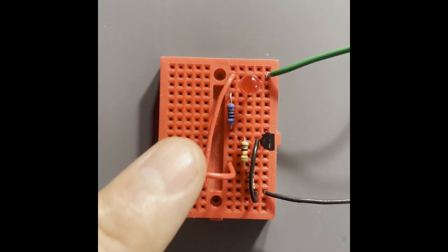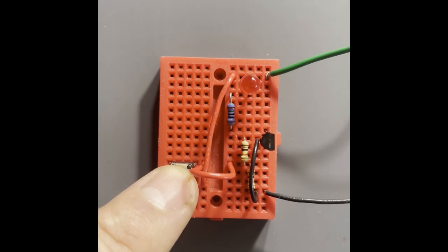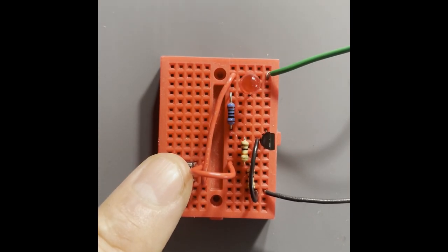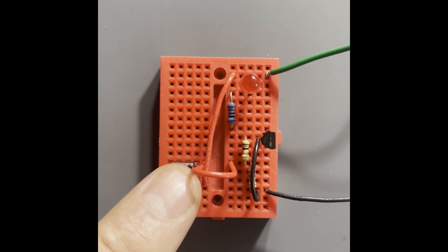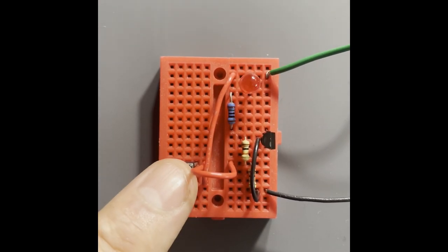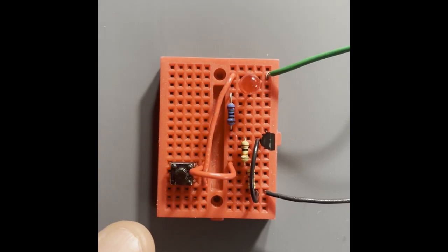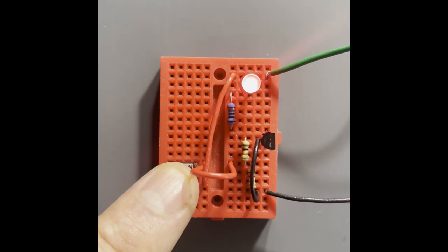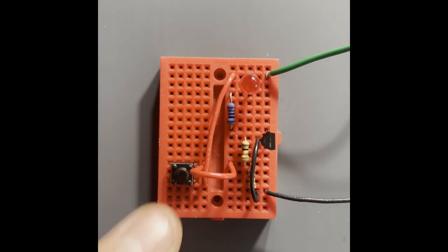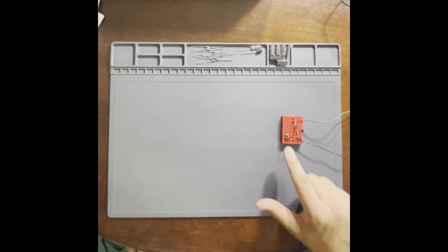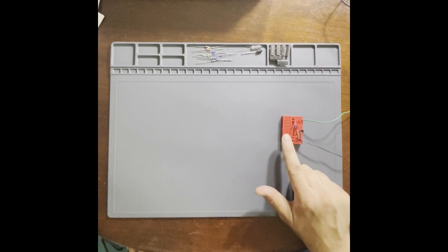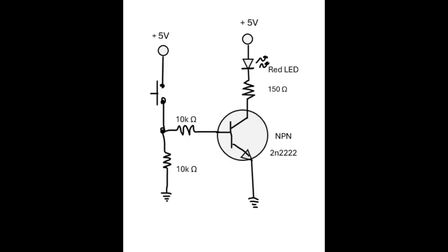Alright, so here is a simple circuit that you can wire up to activate an LED. It uses a commonly available NPN transistor. The transistor being used is a 2N2222. This transistor can handle up to 800 milliamps and can operate at up to 30 volts, which covers many situations. There are other transistors out there that can handle much higher current and higher voltages, but we will just stick with this one for right now.